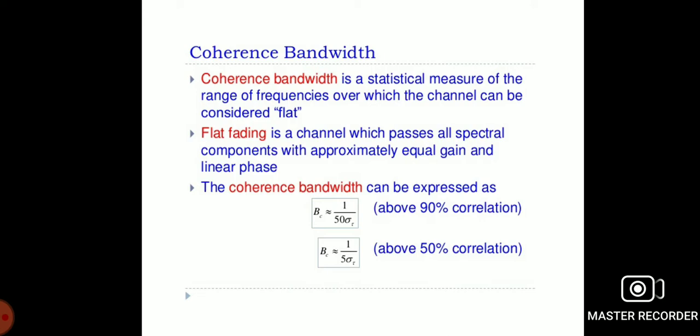Okay, it is a statistical measurement at a different frequency at which the radio channel is observed, that is a flat type. In this flat region, the radio channel passes all the spectral components with nearly equal gain value and with linear phase.